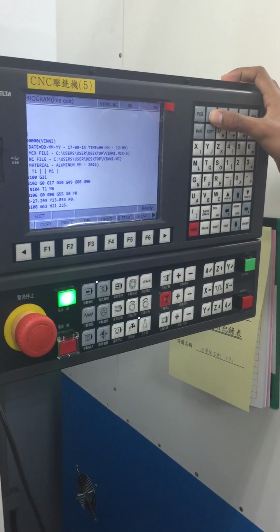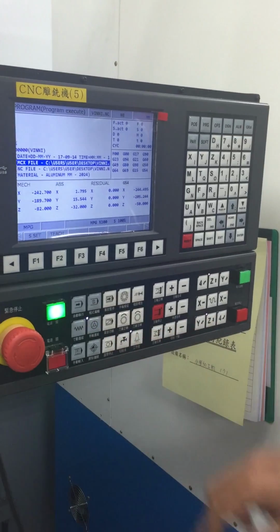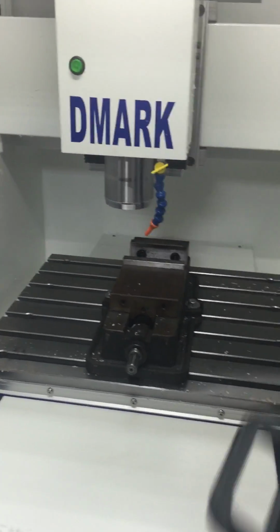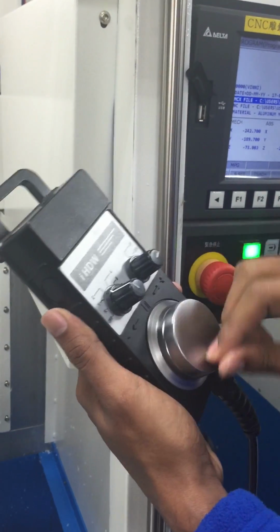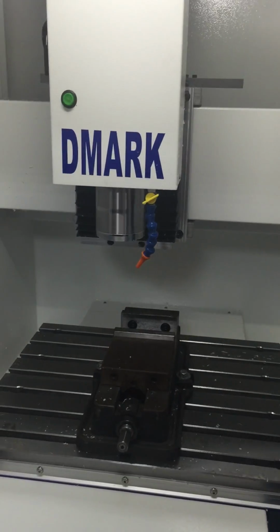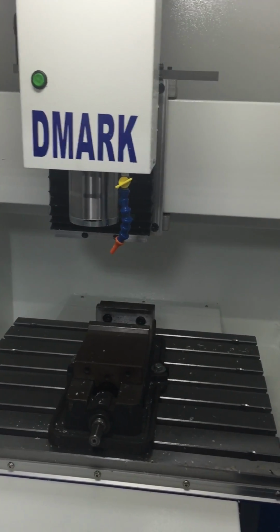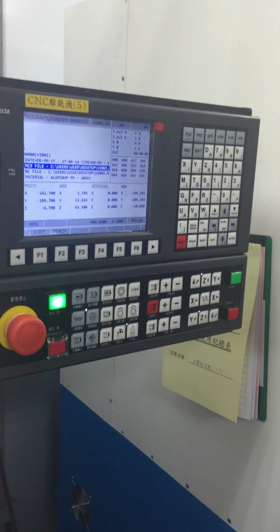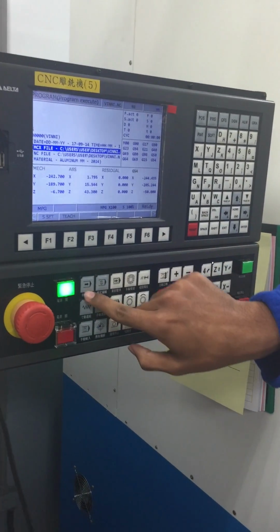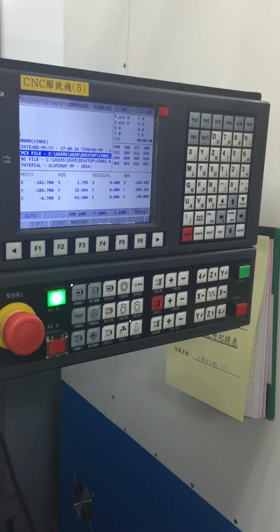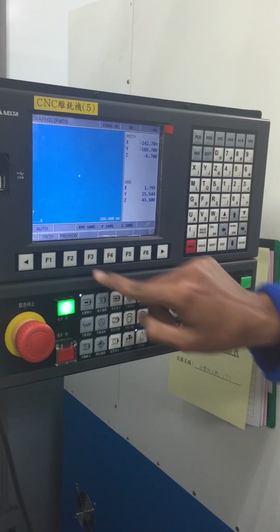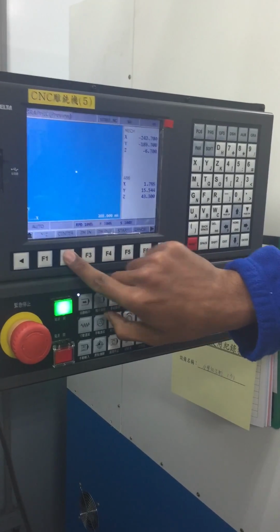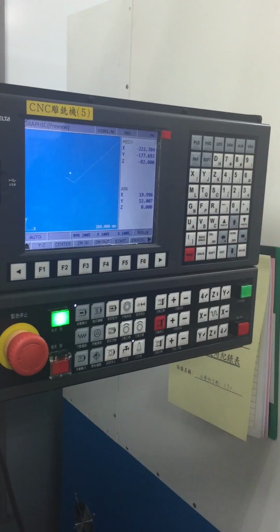So you go back to the program, right? Turn manual. Then you need to raise up your machine, so you go in the positive direction for the Z. So you set it at Z and you go in the positive and you raise it up. Now all your coordinates are set, X, Y, and Z, right? So you need to run your program now. To run that, you need to press the run button, and then you need to see a graph of the situation. So then you press graph, then you go to preview, center, and then you start.